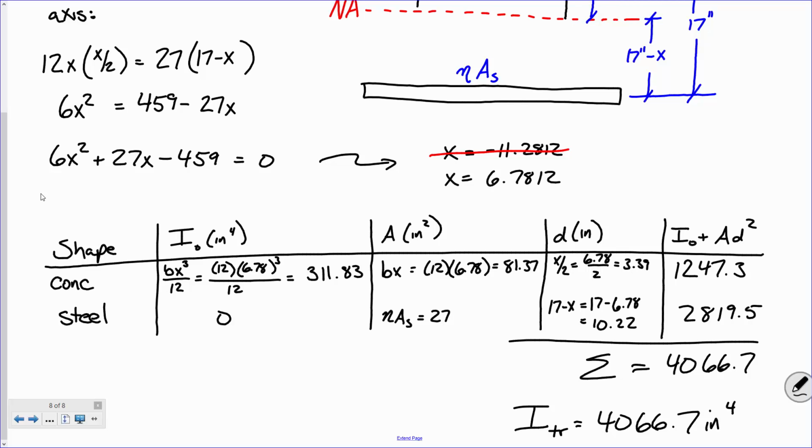How would you calculate the moment of inertia of that? You're saying base times height cubed over 12? Yeah. What is the height? I'm saying it doesn't have one. What we've done is just idealized it as a lumped value at a given point. So its I value is 0.